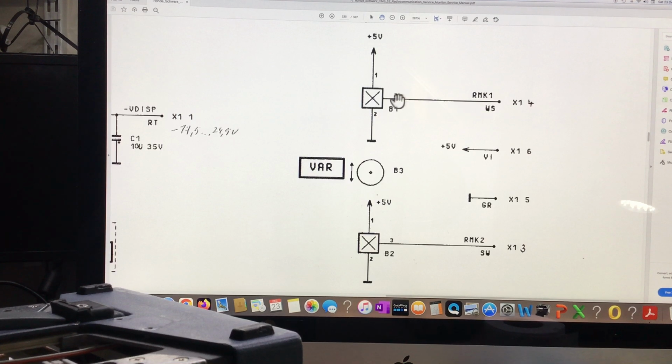Okay, so this is a schematic diagram now for the Hall effect sensors that are used in the spin wheel variable control module. So we've got the magnetic disc, and as it said earlier in our explanation, this disc comprises 12 north poles and 12 south poles, and obviously as a south pole comes via the bottom Hall effect sensor, it would then create a pulse, and likewise at that point there would also be a north pole that would pass this sensor, and that would then generate a pulse out of phase to what would be on the south pole sensor.